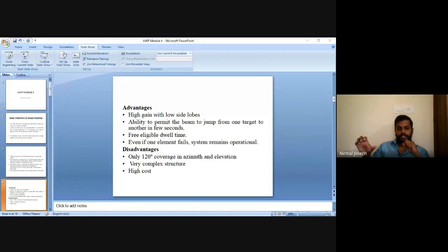That is the only difference. But it won't affect the direction of the major lobe. The direction of the major lobe will be the same since it is not going to affect the interference. If the interference is to be affected, all the relative phase differences of the elements have to be changed. That we are only doing by the use of phase shifters.